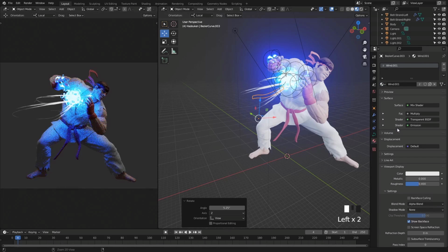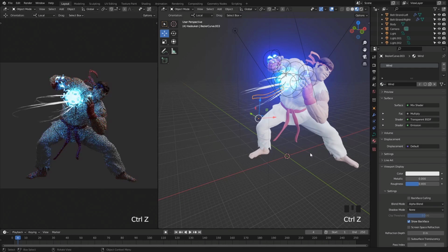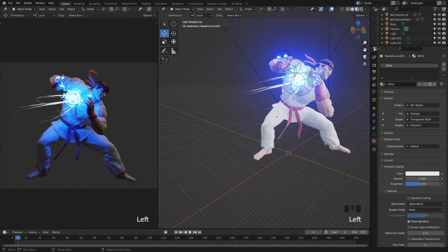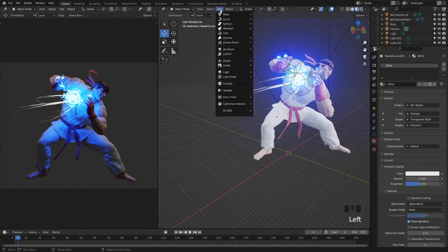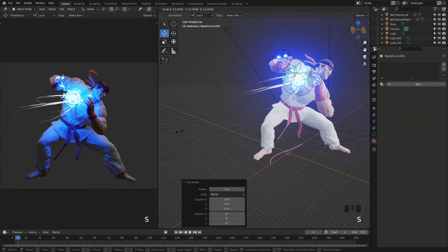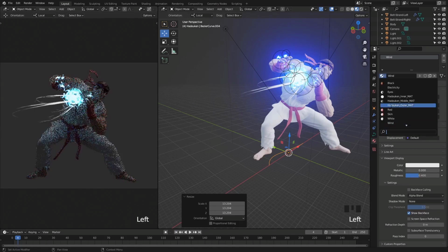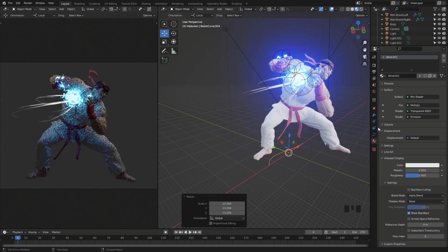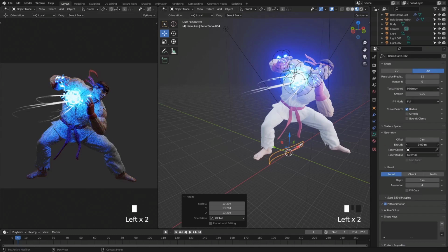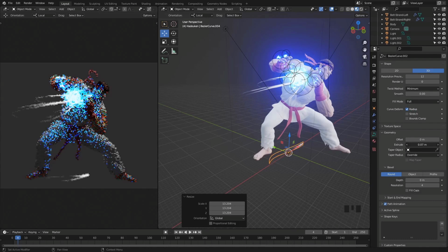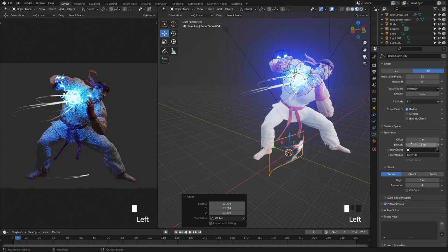Well, okay, now I'm realizing what's happening. I need to deselect that. And I'll add another curve here. The curve, Bezier, extrude out. Let's add the other wind texture. No, not that one. There you go. Wind 01. And let's extrude this out into 0.5. Sorry, not 0.5, 0.05.